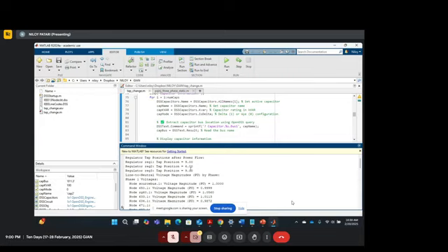Now this interface can also be done with Python. There is a package called PyDSS. So if you write your optimization code or any kind of approach, whatever you want to do, in MATLAB or Python, you just interface with it. The interface is needed because when you want to change some set point, you can send that set point back to OpenDSS.